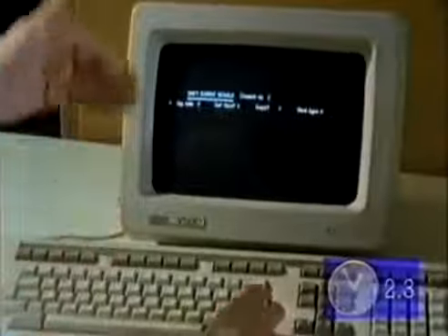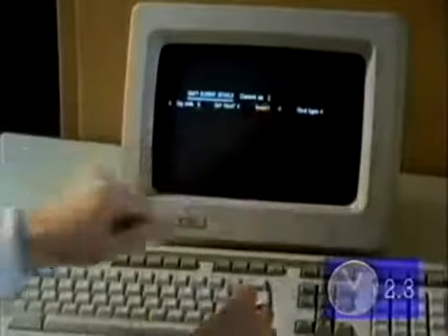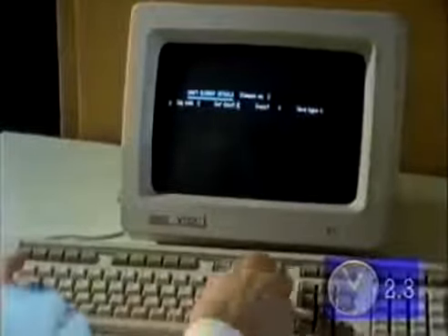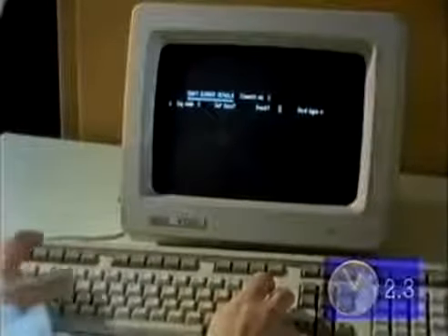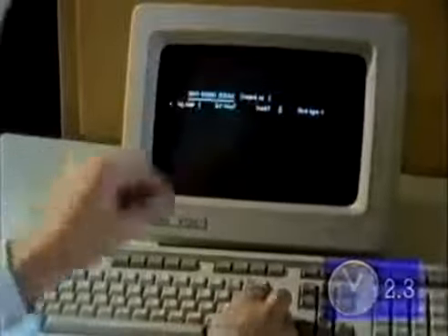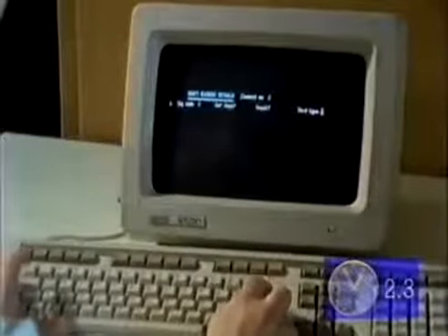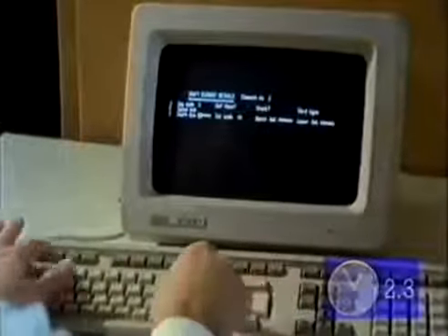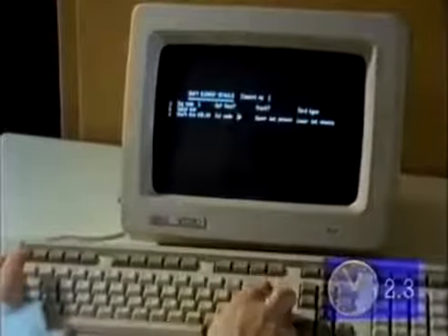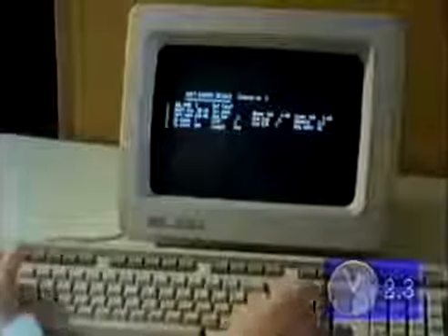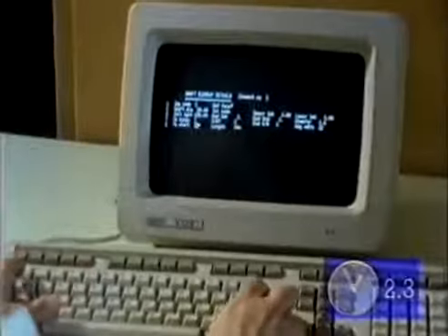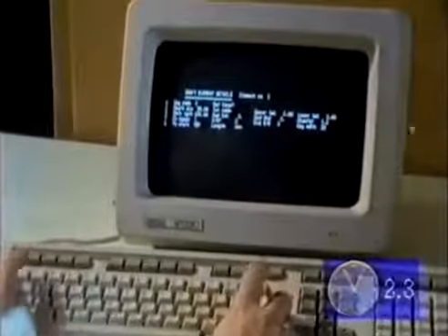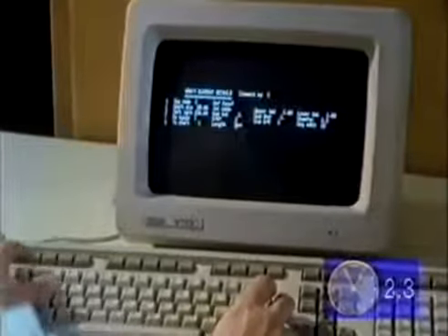This is going to be a plain location diameter. We don't need to specify this. So information for each of the 5 elements of the shaft in turn is requested by the software and punched in on the keyboard. The system asks for very detailed information because engineering parts must be manufactured to a high standard of accuracy, and details of all dimensions, finishes and tolerances must appear on the finished drawing. The whole process takes about 5 minutes.